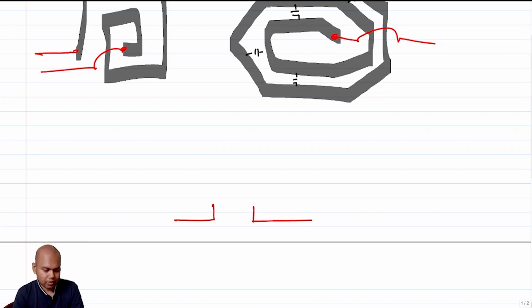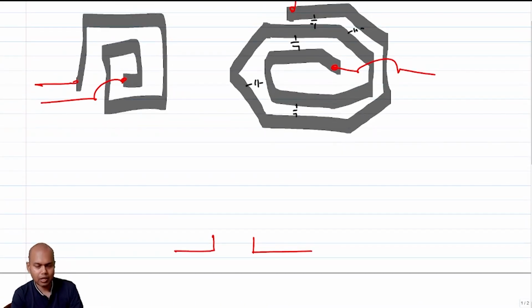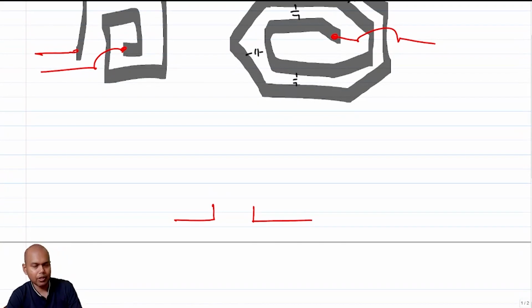So that way both the feed lines also have similar routing, right? In the two structures that I have shown on the top, the input and the output are not taken out symmetrically, and one of the feeds probably will have higher resistance, more losses than the other. Okay, so what if I make a structure like this?